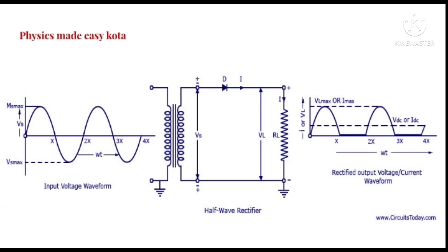Now the junction diode starts conducting, and the current starts flowing. Now we consider another case, when the negative half cycle of the input AC signal is fed into the primary coil. Again EMF is induced across the secondary coil due to mutual induction.